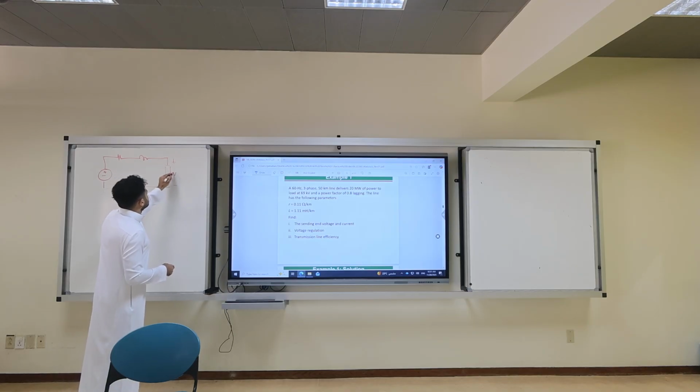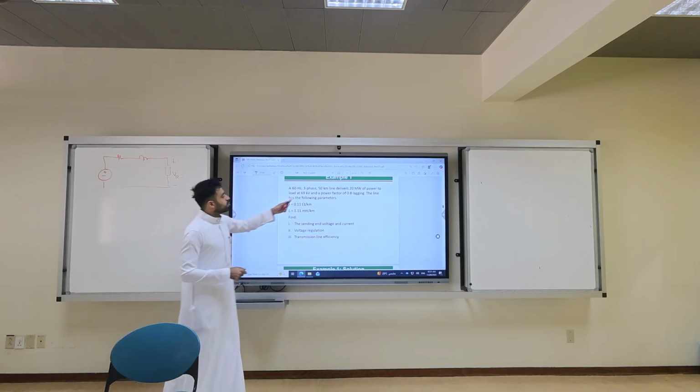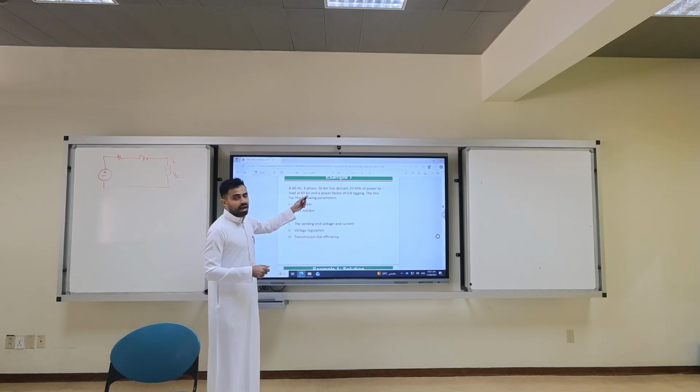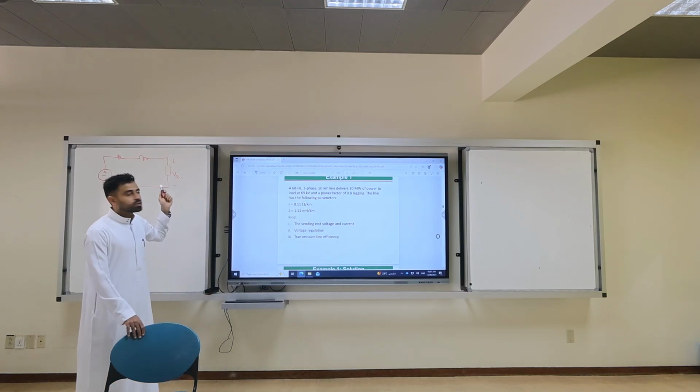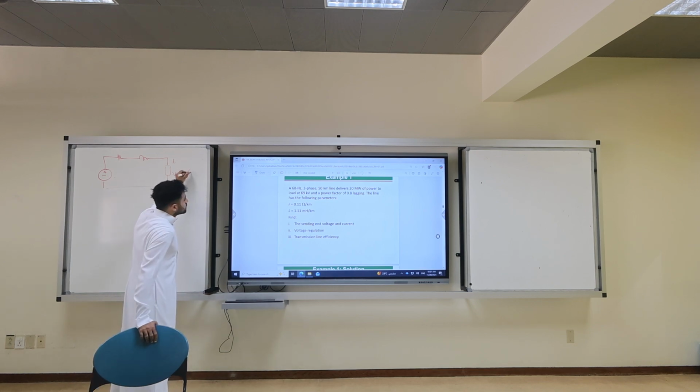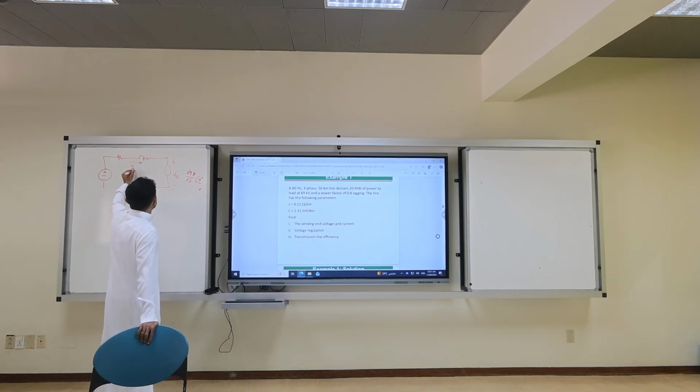What is VR? He is telling you the load is at 69 kV. It is line to line, right? So we draw the single phase equivalent circuit, per phase: 69 kilo divided by square root of 3 angle 0 degrees. Now, I have I line.